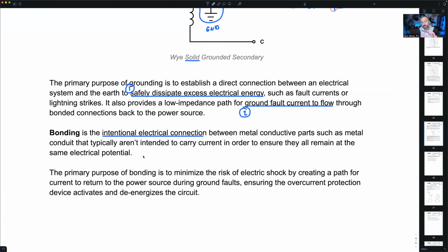It rubs the wire bare so that the insulation breaks. And now the conductive parts of the wire are directly touching the metal part of the case. What happens if I come by and go, oh, laundry's done, and I touch the case if it's not bonded?